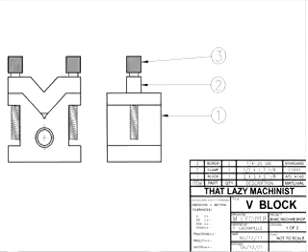The second reason that justifies using reference dimensions is the never repeat rule. And that rule is fundamental for drafting. It states that a dimension can only be seen or calculated in one way on a print. If there's two ways of finding the same dimension, well, that is wrong, and one of those two dimensions should appear as a reference dimension.